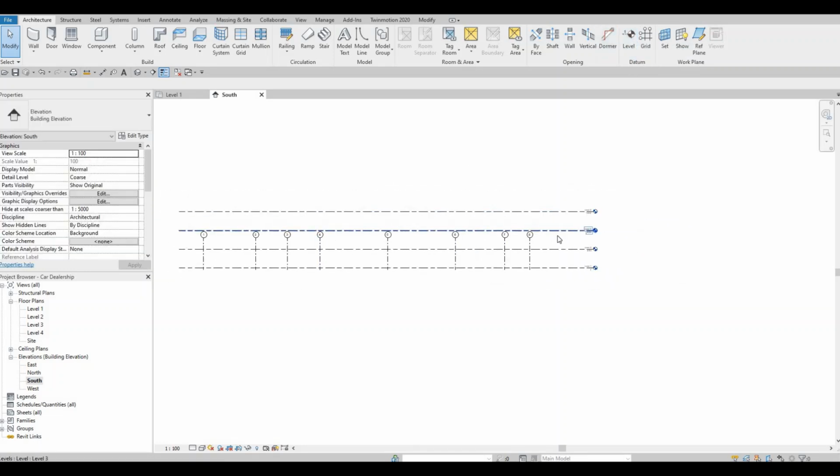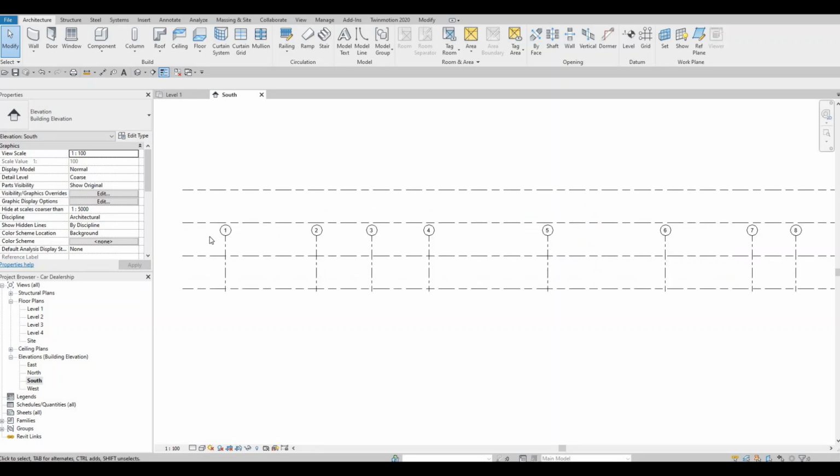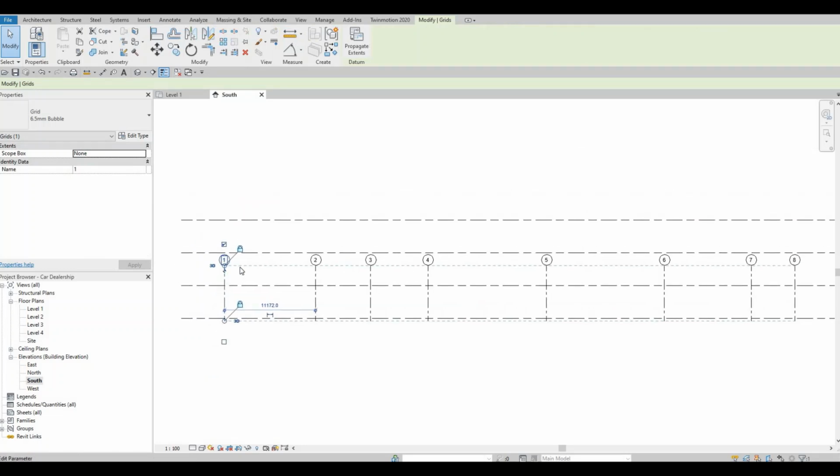Both have pros and cons. I usually like to use the copy command, because what if you have multiple levels like this one? It's very hard to just do it manually like that, level by level, where you need to click and click right here to add multiple. If you just do copy, it's very easy. You just need to copy. You can type it. You can even do an array of that. So here we could select that one now.